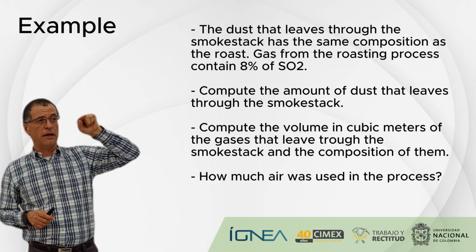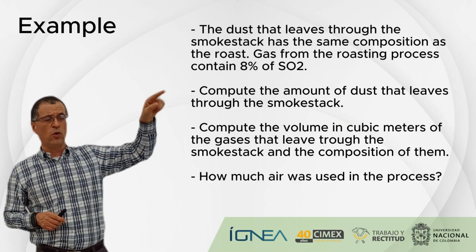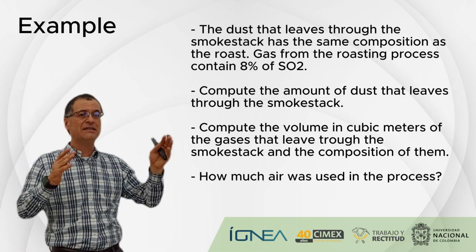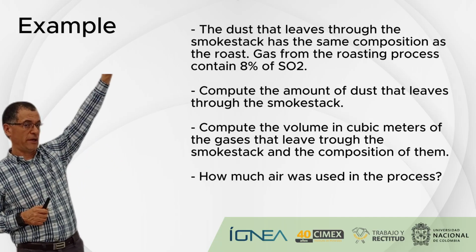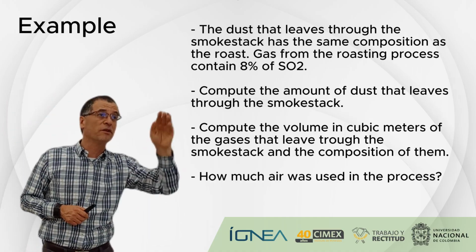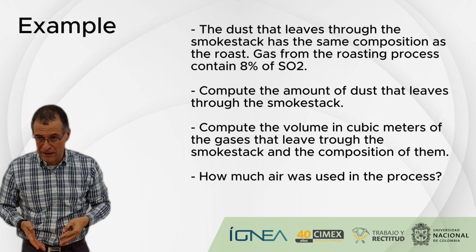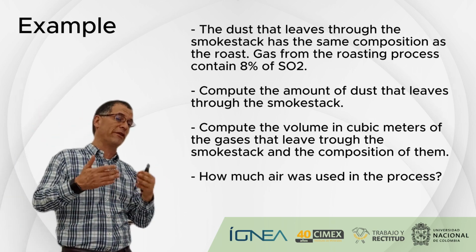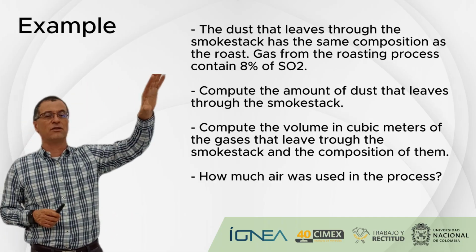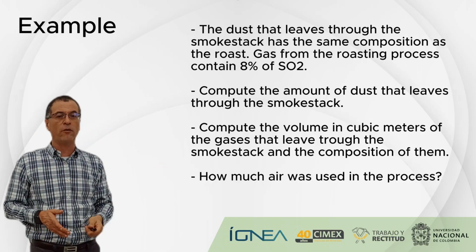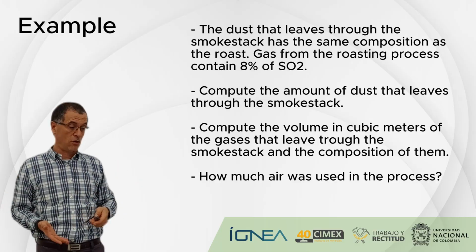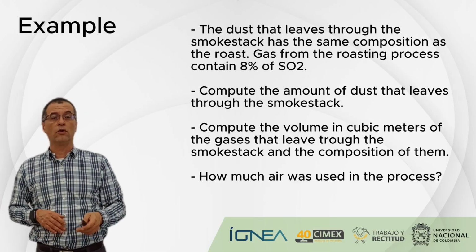We are going to obtain 8% of SO2 in the gases in the chimney, and we have to define the characteristics and the composition of the gases. We have to define the total air that we use in the reactions, and the final reactions. This is the problem we are going to solve now.